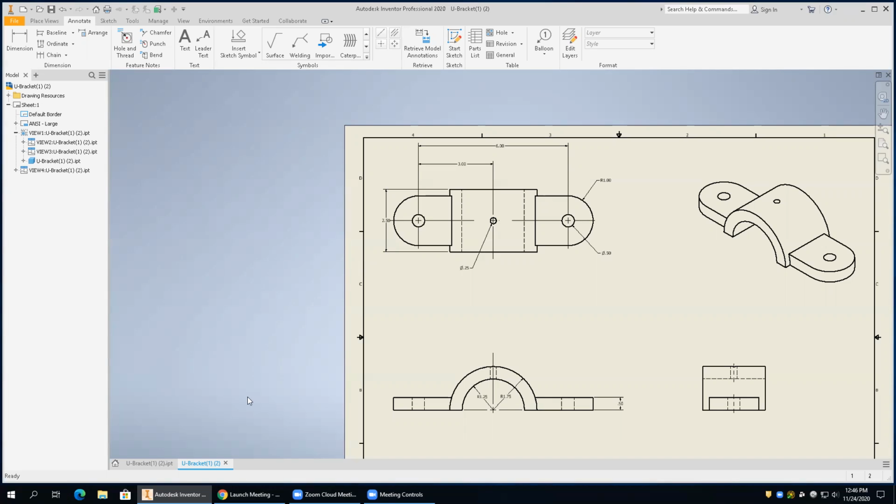minimalism, all right? We want as minimum dimensions as we can get by with. Now you might actually need some dimensions here, and some dimensions here, just because of the nature of the part. We didn't need those in this case, right? This case was totally everything we needed right there, okay? So I could give you this drawing and you guys should all be able to draw this. Okay, we good with that?